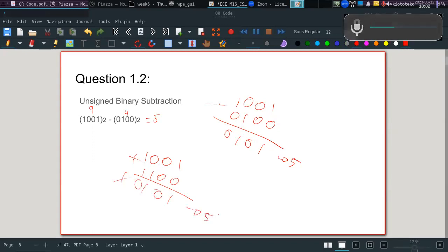There is no reason why subtracting the numbers as they are in base 2 shouldn't result in the same thing. But the reason we use adders is because usually in computers you only have adders, not subtractors. So the only way of subtracting two numbers as an addition operation is to get the 2's complement of the one you're subtracting and just add it.